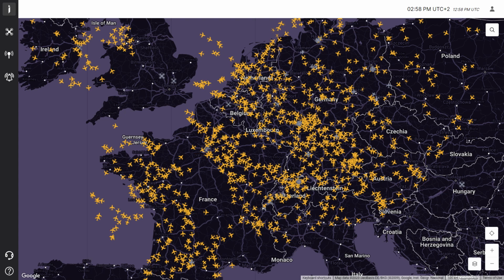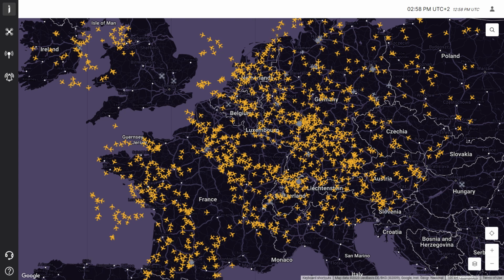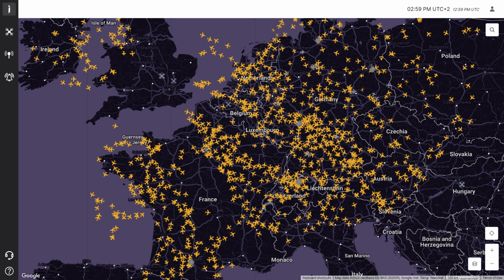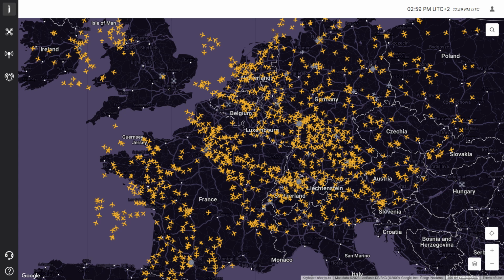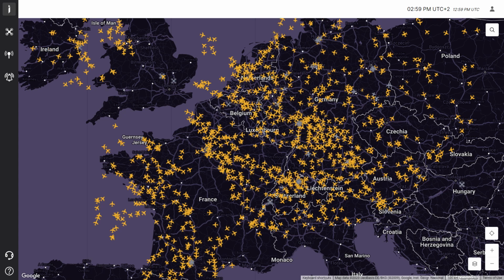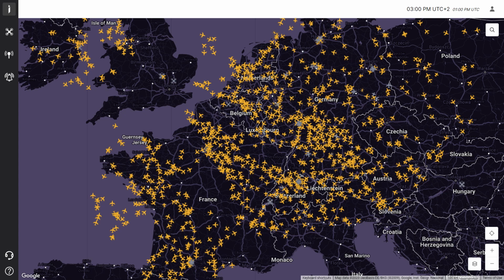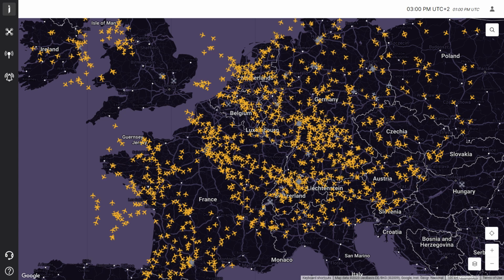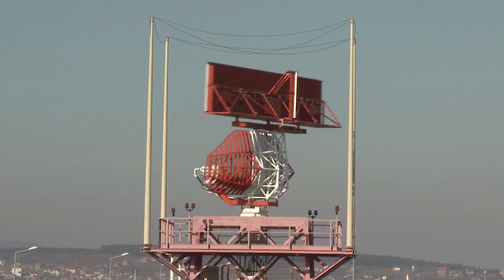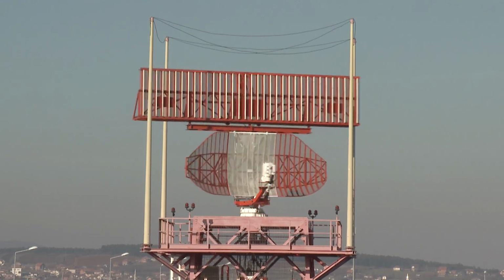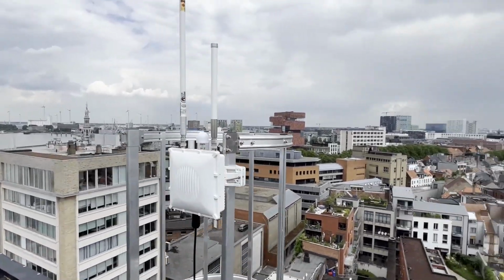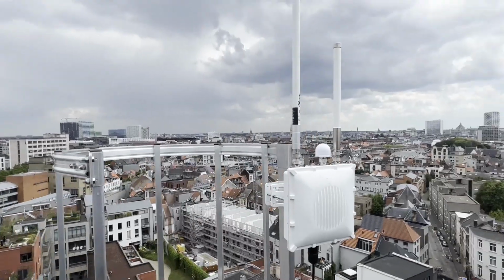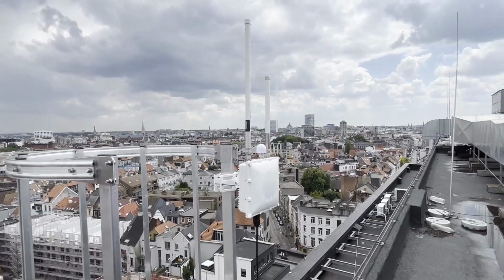The growing network of INVOLI's receivers is collecting large amounts of information, which can be useful in many ways, from traffic monitoring and warning to estimating mid-air collision hazards for specific locations. Today we want to talk about the process of determining an aircraft's position based on multilateration. Compared to expensive and difficult to set up primary and secondary radars, multilateration is a reliable and cost-effective alternative way of determining the position of the aircraft that emit transponder signals.